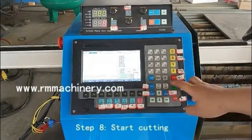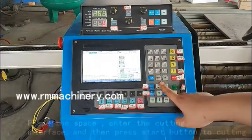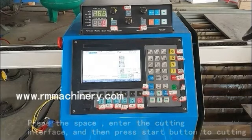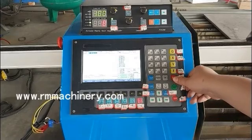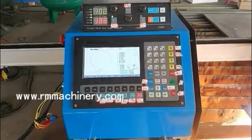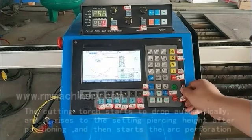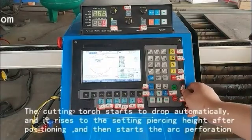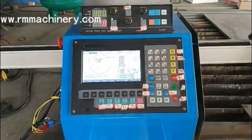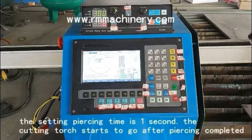Step 8, Start cutting. Press the space key to enter the cutting interface, and then press the Start button to cut. The cutting torch starts to drop automatically, and it rises to the setting piercing height after positioning, and then starts the arc perforation. The setting piercing time is 1 second. The cutting torch starts to move after piercing is completed.